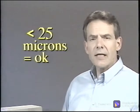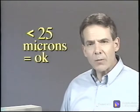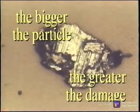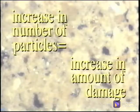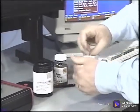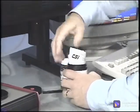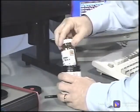Clean operations. If particles are less than 25 microns, the equipment is generally operating satisfactorily. Secondly, the larger the particle, the greater the damage, and an increase in the number of particles indicates an increase in the amount of damage. When a sample is abnormal, then send it to an off-site lab to analyze the particle type and determine whether it is a contaminant or actually a wear metal.